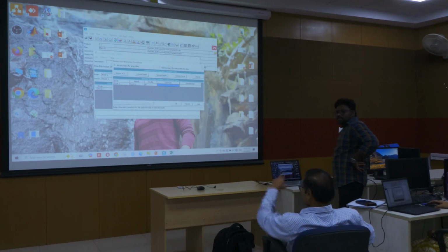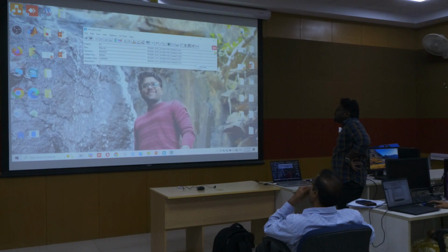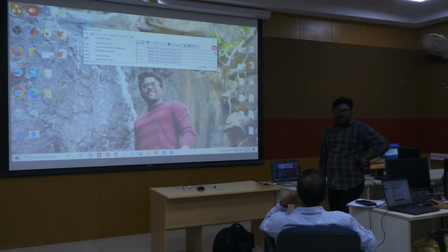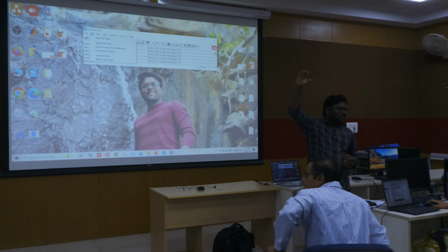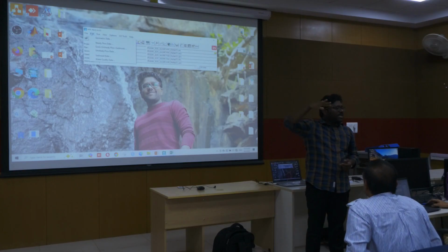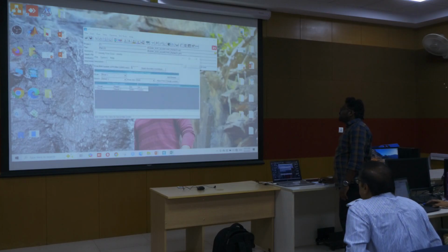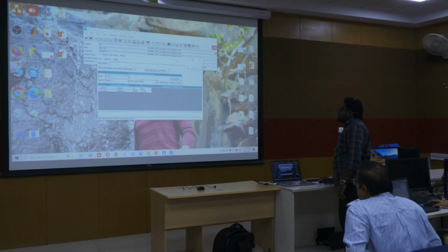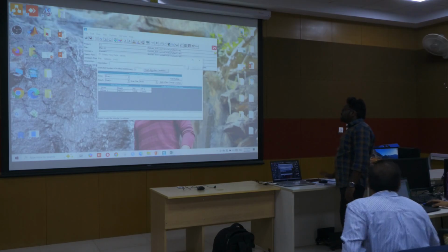Please repeat the steps. So what I am telling is, if we have the peak flow, for example 20,000 meter cube per second, now see at that 20,000 meter cube per second, what is the inundation area? For that, just go to edit, steady flow data. Here, the last time we forgot to mention the boundary conditions.